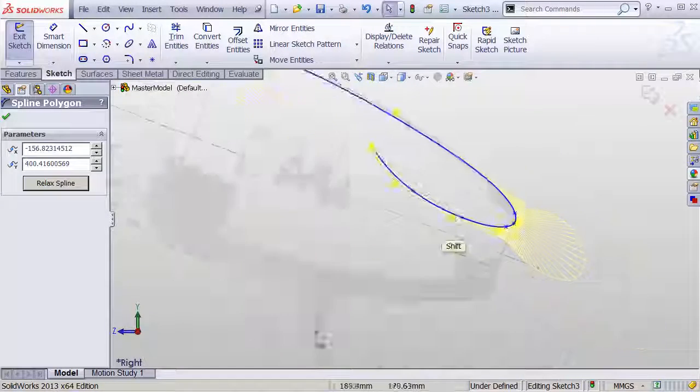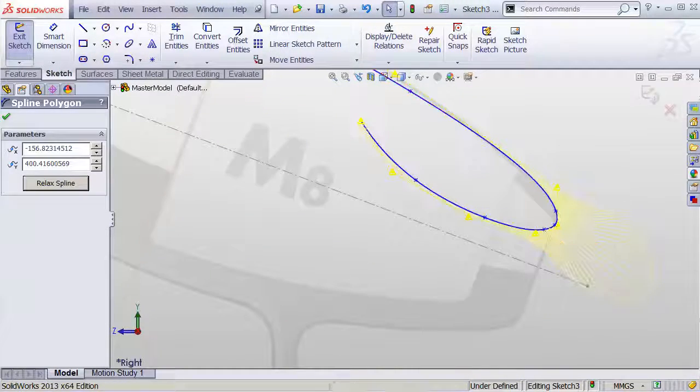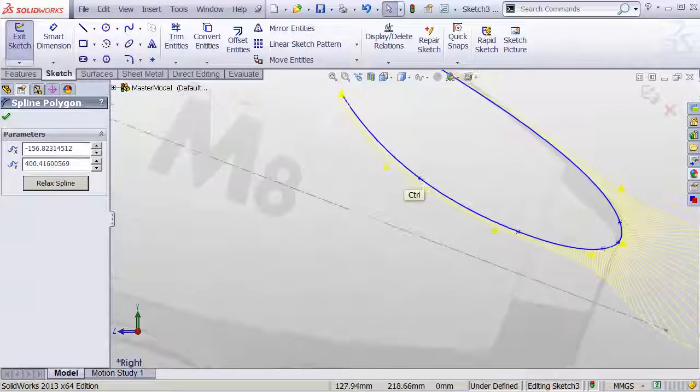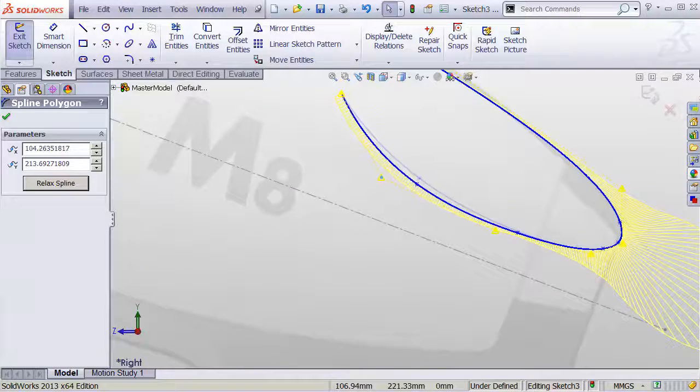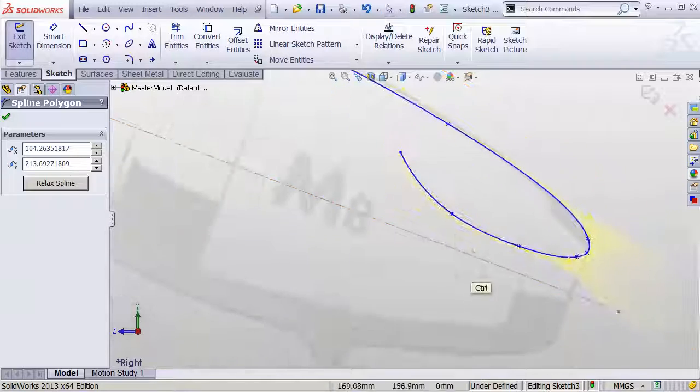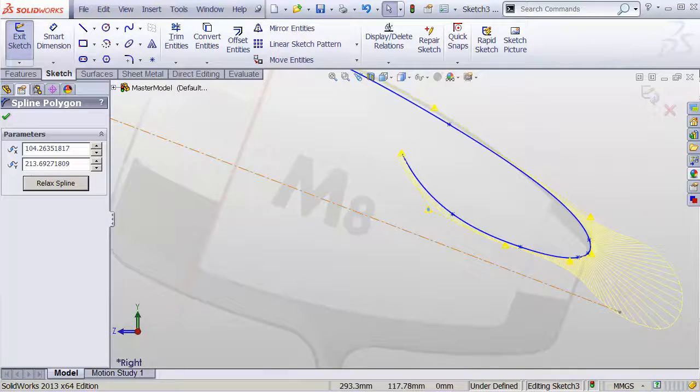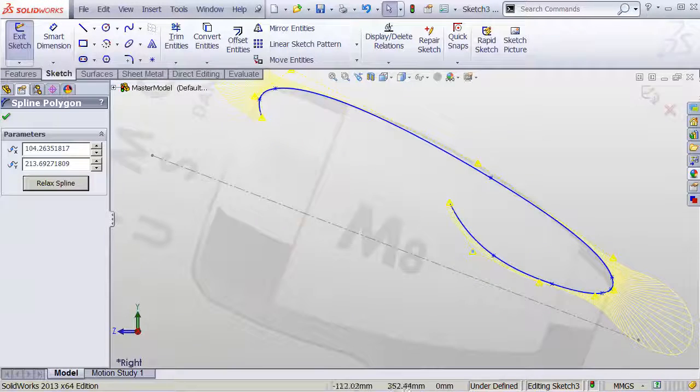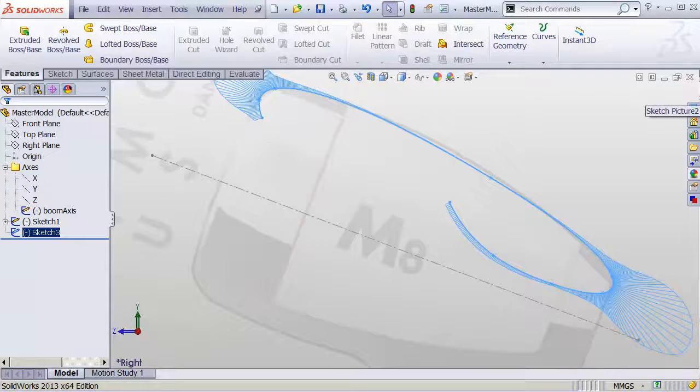Okay, so essentially this inner part is kind of shaped like a horn in a way. This is going to be the port coming out the back. And the reason we shape it that way is, well, to relax the air coming through so you don't hear port noise as the air flies in and out of there. Okay, so I'll exit that.